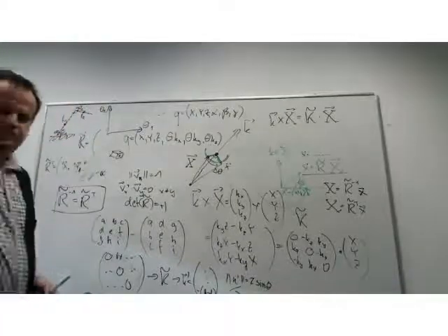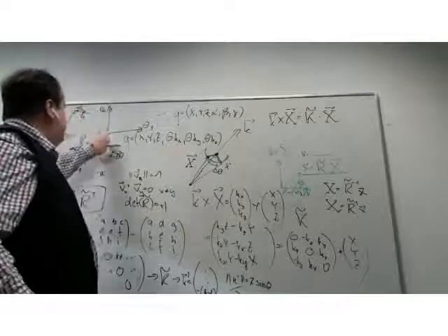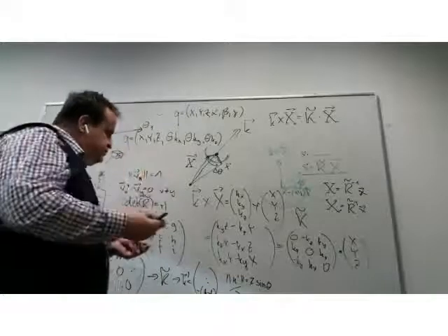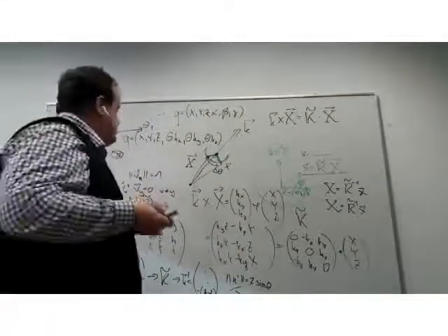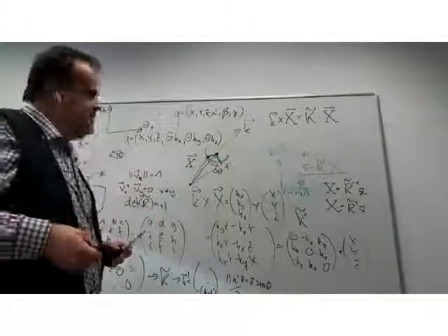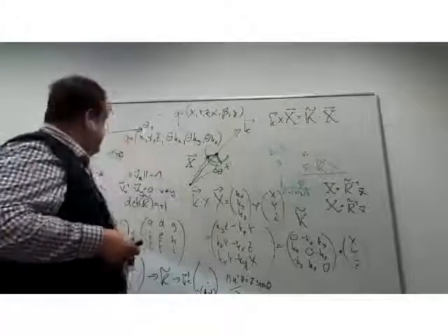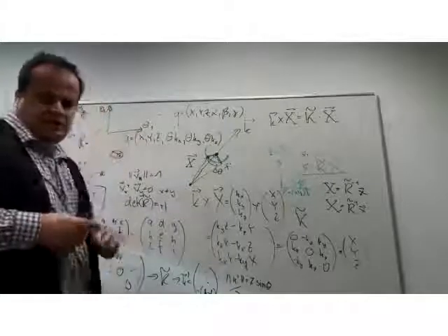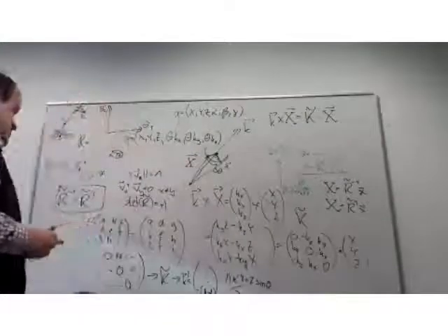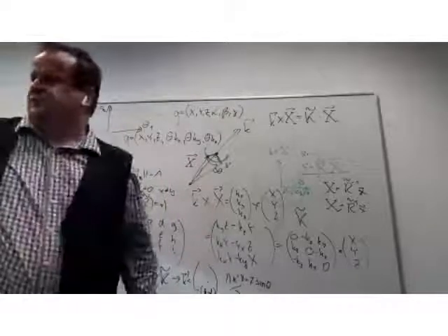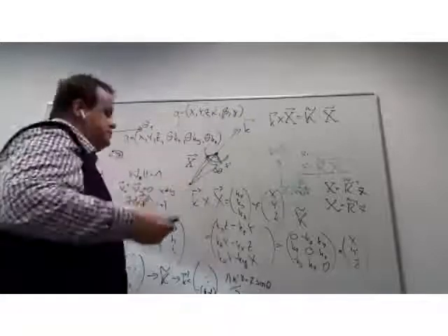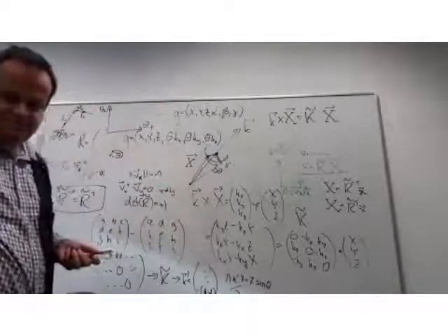The configuration of a manipulator is defined by the motors generating motions of the robot, which are usually the joint parameters. In case of a rotational or revolving joint, or it can be a translation if we have a telescopic joint which slides in and out. So configuration space defines basically now all possible configurations of the system.